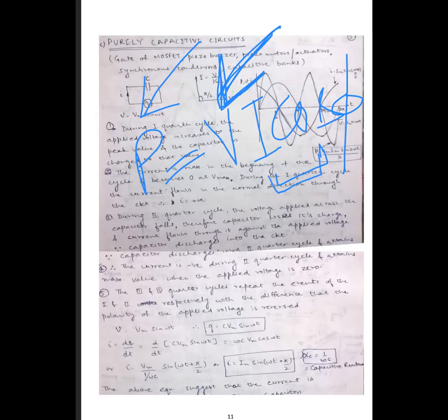So there is a relationship between the current and the power factor. Okay, so the government has allowed the power factor to be 0.8. The power factor is always less than 1. And if the inductive load is there, the power factor decreases, and in the industries, induction motors and inductive loads are more, so the power factor reduces.